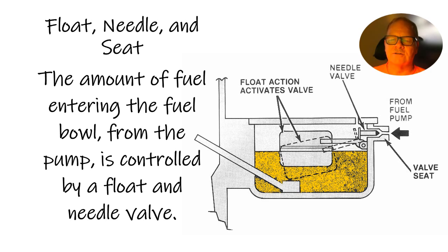Well, that's kind of silly, because the fuel filter, unless it's got a completely stopped up sock in the tank or something, is not going to keep it from starting, but it will cause you to lose power when you're trying to pass a car or something like that.